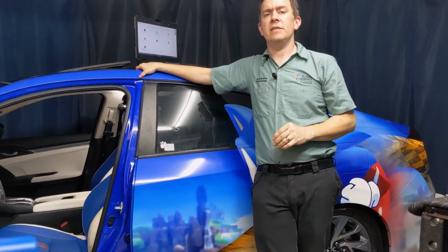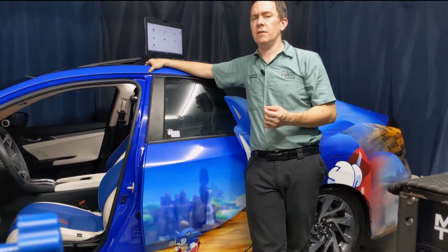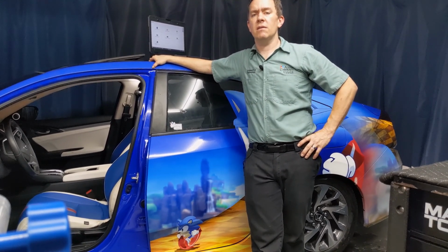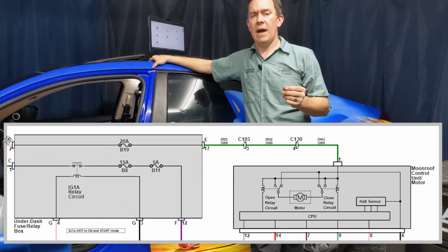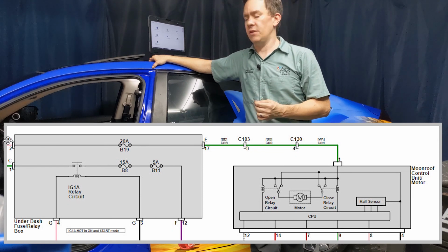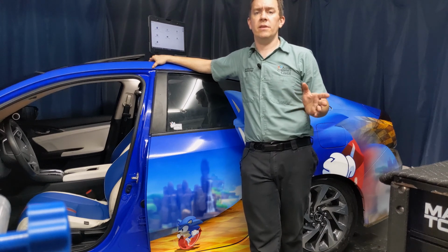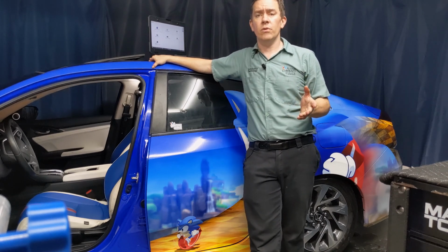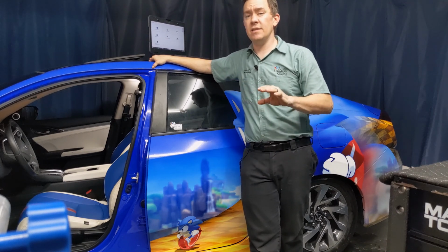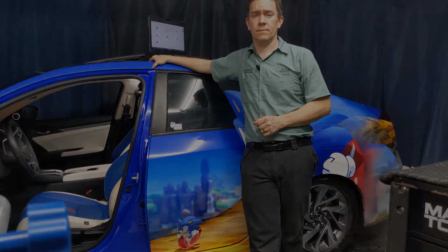So I've cleared out the DTCs from that last experiment we did, and I realized that also showed me that LIN communication is necessary for the operation of the moonroof. It turns out, since the moonroof doesn't use a switched power connection, the control units are only going to operate when LIN tells them that the vehicle is turned on. When LIN's shorted to ground, the control units don't know that the ignition's on, and they're not going to operate the moonroof. One last note, shorting a communication wire is a quick way to disable communication networks, and it's not going to damage those control units.